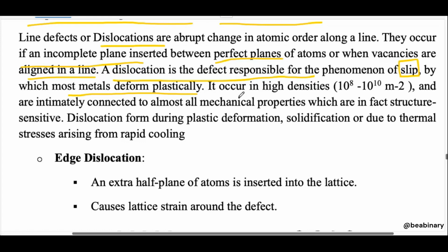When you apply the load, then if after releasing the load the body comes to its original position, then it is an elastic deformation. For elastic deformation, they can regain their shape and their position after reducing the load. And in plastic deformation, once you apply the load and they have deformed, they will not regain their position. That is known as plastic deformation. So you were right, but just correct yourself: it's a load, not a stress.